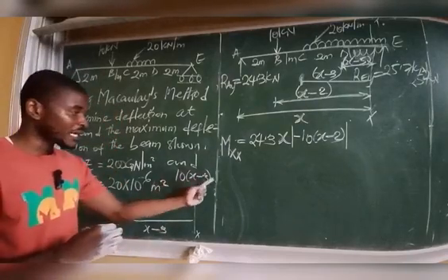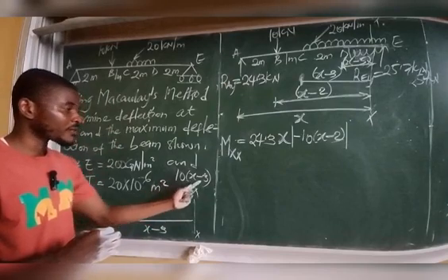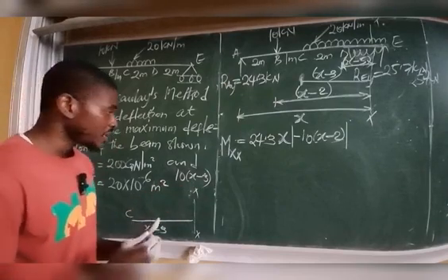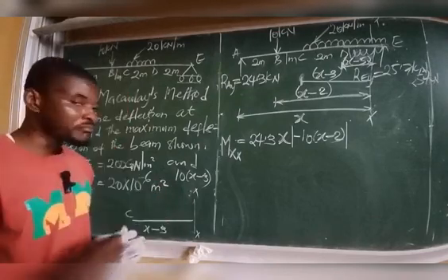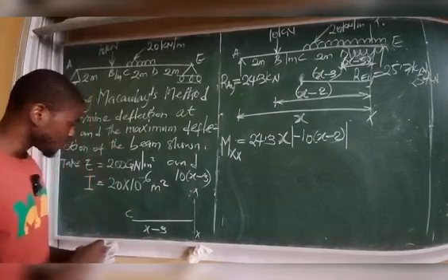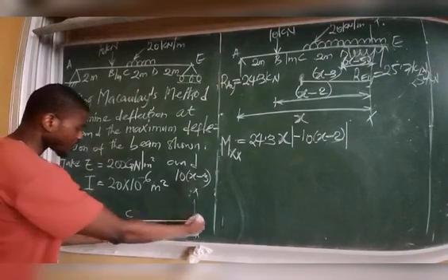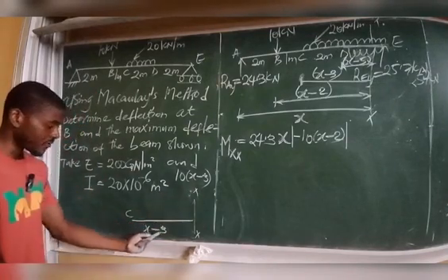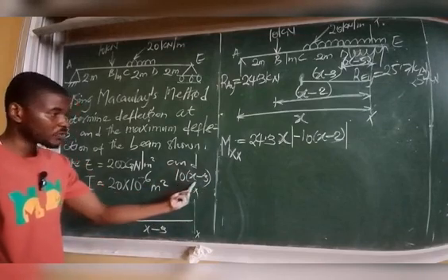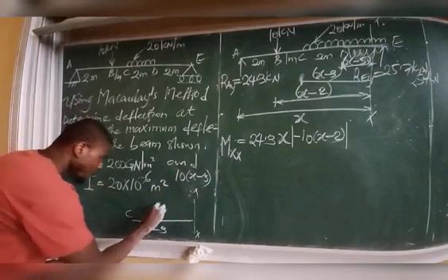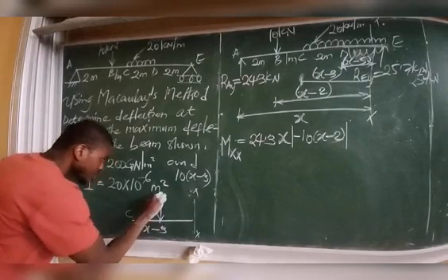This is a point load and not a moment. So 10 into x minus 3 is a point load. And we said that after getting this point load, place it at the middle of the length covered by the UDL. So if here is point C and here is the point of section, this is the distance of this UDL, x minus 3, about the point of section. I've converted this UDL to a point load, I have 10 into x minus 3, and now I have to place it at the middle of the length.